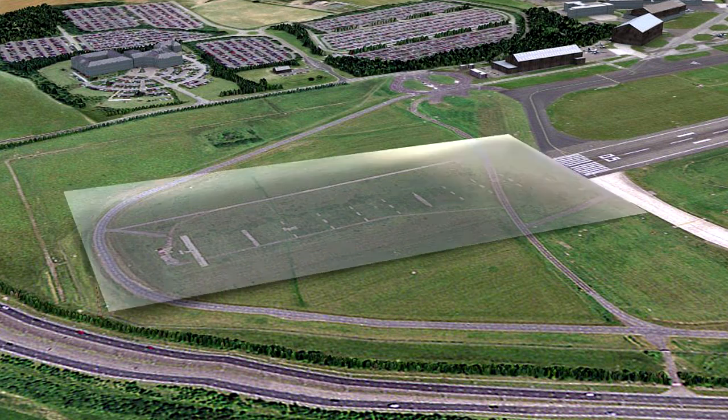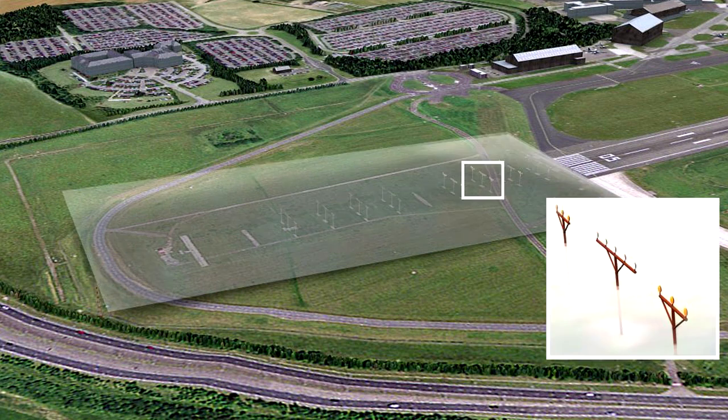The clearway is actually the area underneath the clearway plane, which extends from the end of the runway with an upward slope not exceeding 1.25%, above which no obstacle or terrain protrudes. However, threshold lights may protrude above the plane if their height above the end of the runway is 0.66 meters or less, and if they are located to each side of the runway.